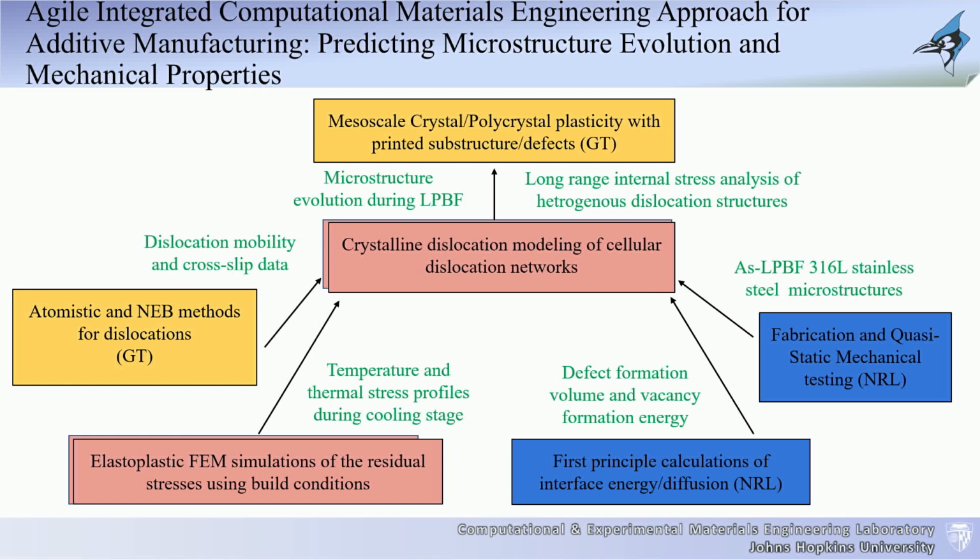Well, for one, we need the information related to the loads that are generated and the temperatures that are generated when a laser passes through and this material starts cooling down. Because the cooling down of the material induces a significant amount of residual stresses that will affect the evolution of the dislocation microstructure during that cool down stage. So we need that information, and I'll talk about that in a minute.